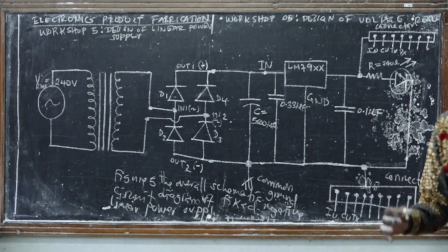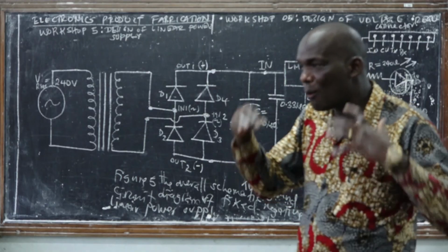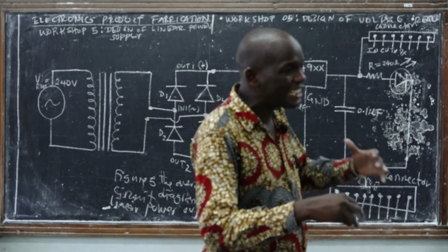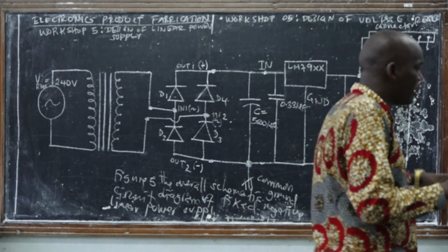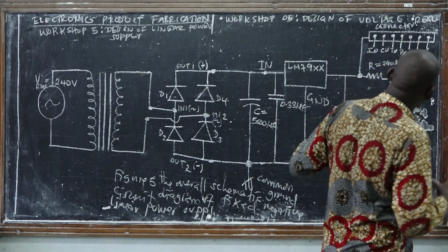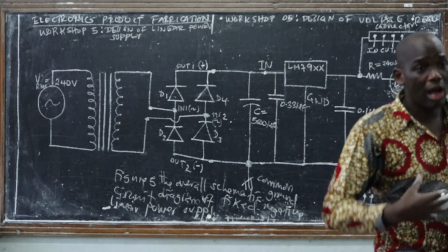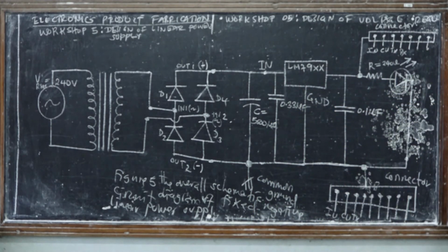The total operating power for your system is 2 ampere. For that scenario, you may not use a single linear positive power supply to power that system because it will give you only 1 ampere. So the other parts of your design will have insufficient power supply.